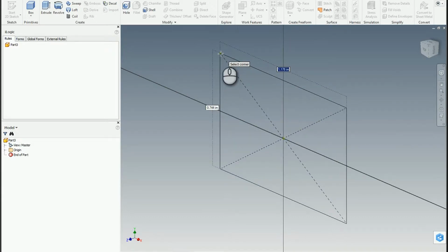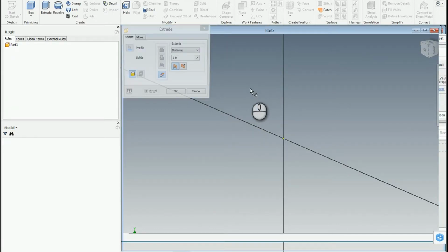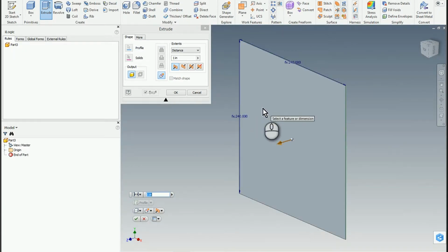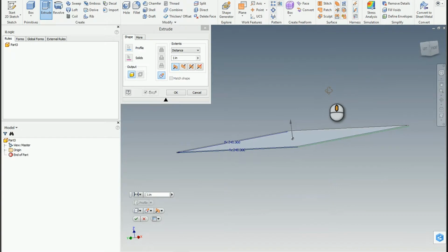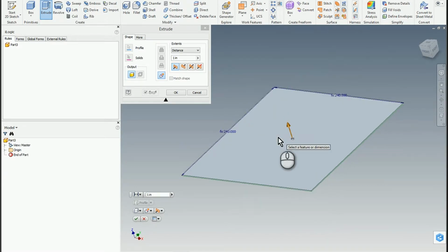And this is where I'm going to use my x size for this one and my y size when I hit tab. So I just type in x size. You can also, once you type in any character, notice the arrow at the right. That's where you could then hit the backspace and choose your parameter as well, and any named parameter that you have is accessible. Hit enter, and so now what it did was it created the size of my plate, and here's the trick. You don't have to do this, but what's helpful is I like to orient it exactly the way that I want it to show up within factory.